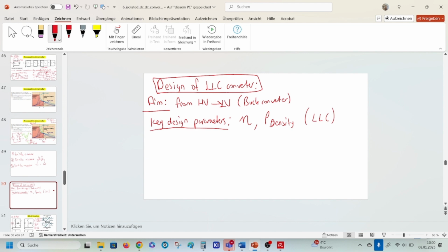this idea to operate the circuit at resonance below or above, it's very sensitive because your load changes simultaneously. It's not constant. If you connect the microprocessor with 5 volts, for example, the microprocessor requires different output currents. And this curve changes very fast.